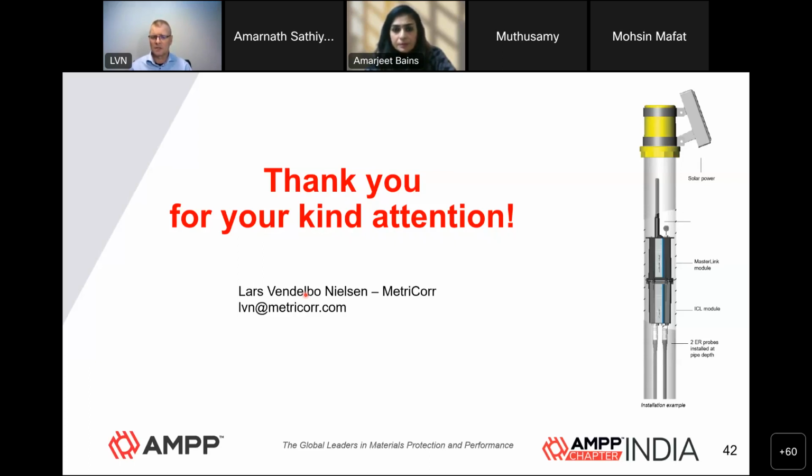I actually think I understand the question, and it's in the same family as the first one. How do we know that our cathodic protection system is actually working? I illustrated a conflict when you measured the potential alone and compared that with the corrosion rate. And I think that has been the intention of this whole talk: to trust a little bit less on potentials, a little bit more on currents and corrosion rates, using this system in combination and focusing on the corrosion rate.